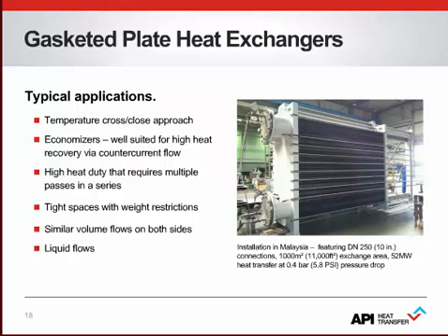Also, if you want to heat or cool the liquid over a bigger temperature range, for example from 10 to 100 degrees Celsius, a plate heat exchanger shows its compact advantages, as you can build multiple passes in one heat exchanger easily. The high efficiency is optimized when the volume flows on both sides are not far from each other and the flow is all in liquid stages. Gases can be handled in a gasketed plate heat exchanger as well, but to a low extent.